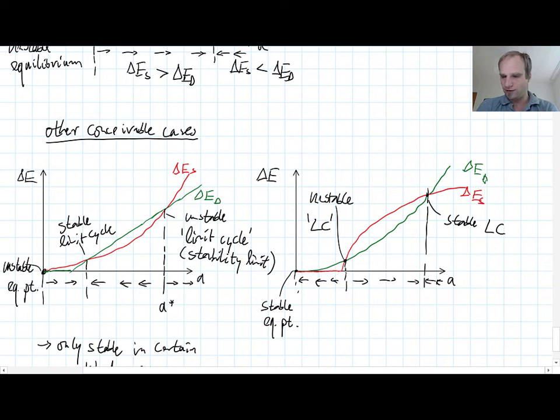So this is an interesting situation because linear theory would then tell us that this equilibrium point is stable, but in effect, if there's a sufficiently large, not zero, not vanishingly small, but finite, but perhaps small initial perturbation, so some perturbation that gives us the situation that we have amplitudes larger than this threshold, then actually the vibrations grow until this limit cycle.